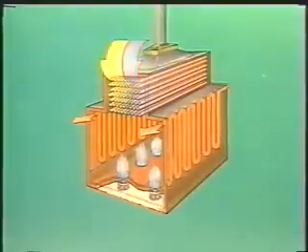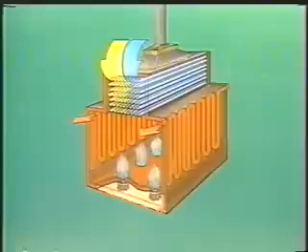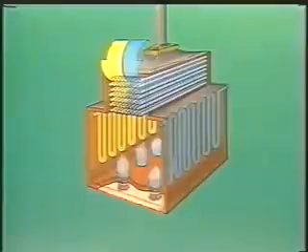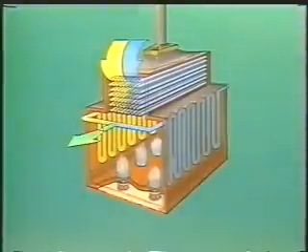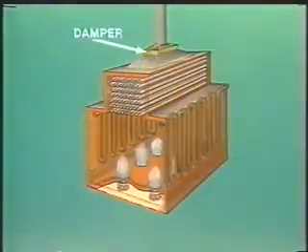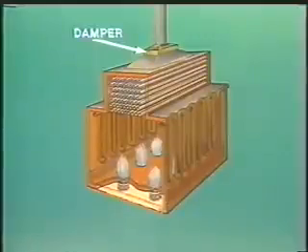The tubes which carry the process flow are generally divided into passes or coils. If the passes are balanced properly, each pass receives the same amount of process flow and absorbs the same amount of heat. After the process flow is circulated through the passes, it is rejoined at the outlet. In the stack of the furnace is the damper. The damper adjusts to control the flow of hot gases out of the furnace. This upward flow of hot gases is known as the furnace draft.